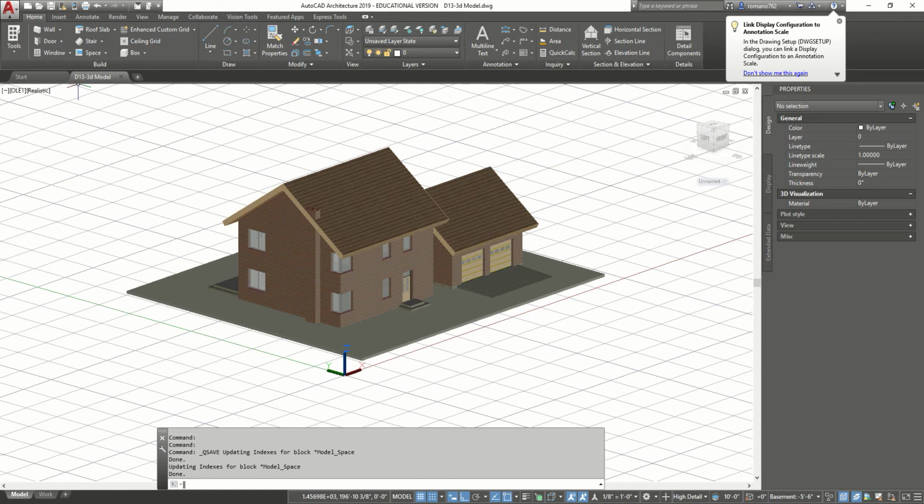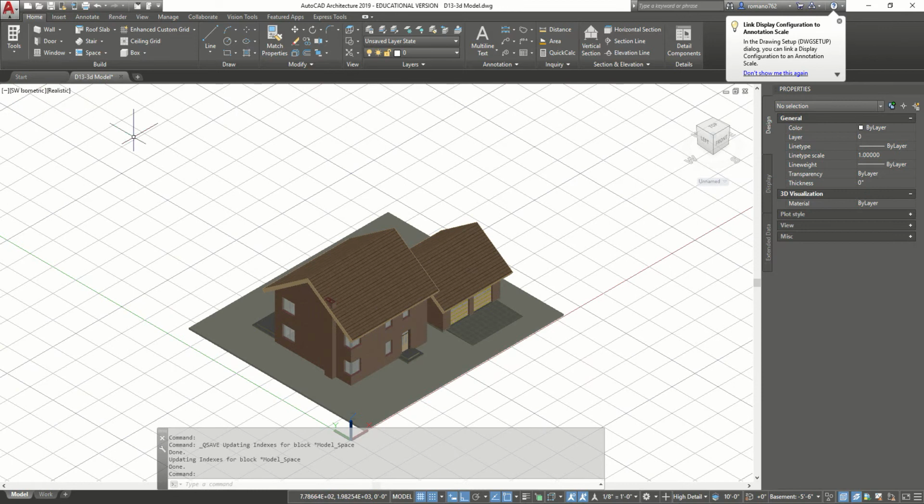So now we can start setting the perspective view with orbit, like I showed you. Using the view cube, we could change the view to southwest. This corner here is going to be southwest isometric. You could click them using the cube, or you could click them using the icons over here. Whichever you want, you're able to do.